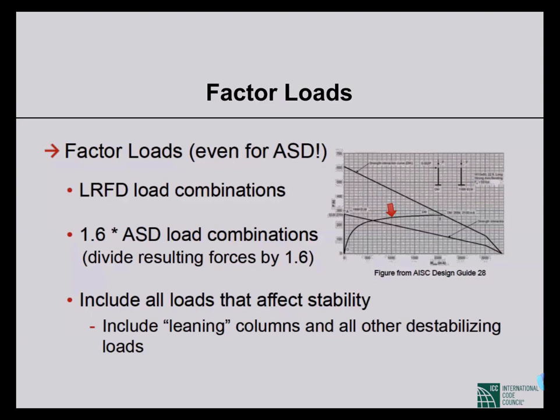But that superposition is not valid for direct analysis, since we will consider both types of P delta effects. That kind of superposition is no more valid.